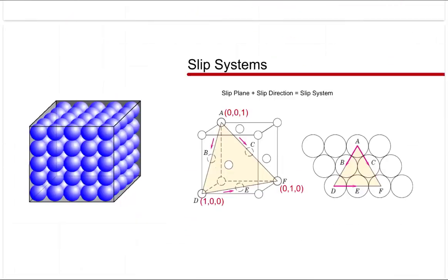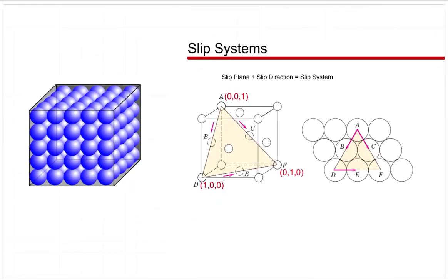Now to understand what actually is happening in slip, I am showing you one crystal. These are the different atomic planes. Now if I apply a tensile stress here, what will happen? These planes will slip on each other, right? This plane may slip, and after slipping the length will increase. So this is a perfect crystal without slipping. Each material has some kind of slip planes in it.